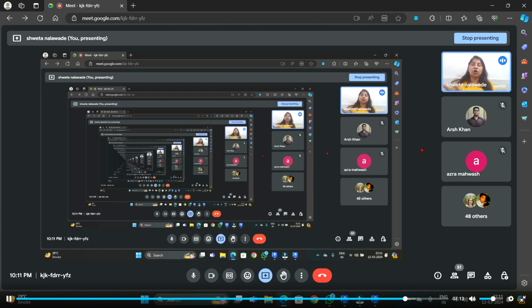Another option is to use model lines or annotation lines as reference lines while you're designing. When annotation or model lines are used, it's easier because they won't bother you the way grids do, as they are not the same elements. The visibility of those can be controlled while extracting a particular data. In the case of grids, the visibility can also be controlled, but it would be done using different filter options.